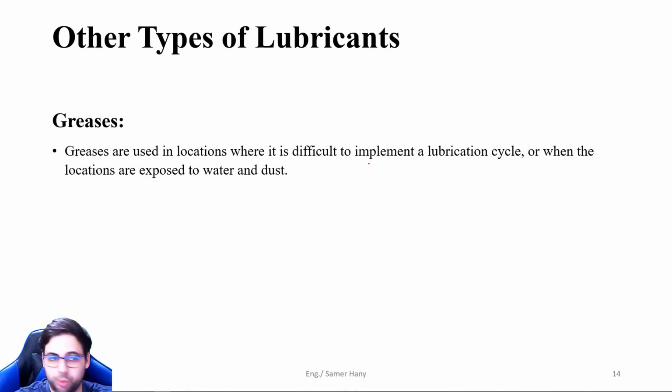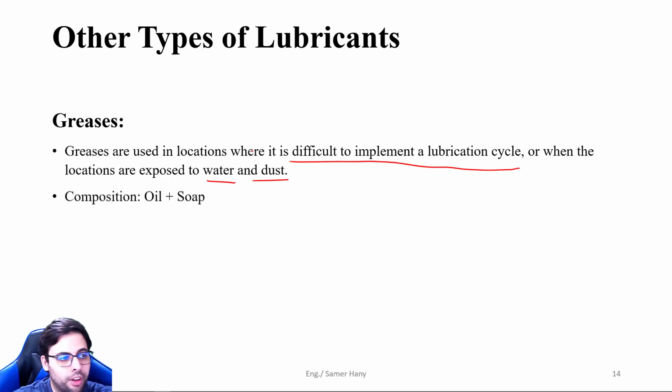So when do we use grease? When it's difficult to implement a lubrication cycle, or when the locations lubricated will be exposed to water or dust or the atmosphere in general, and not in a closed system like most machinery. What's the composition of these greases? It's oil plus soap.